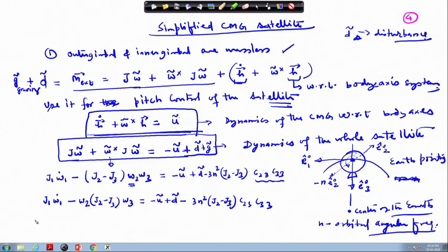Okay. So, omega 2 times omega 3, this can be written as omega 2 equal to theta 2 dot minus n and omega 3 equal to theta 3 dot plus n times theta 1, okay. And all the second order terms will be ignored. So, we look for the second order terms. This multiplied together forms a second order term, this multiplied together forms a second order term, this and this multiplied together does not form a second order term, because this is minus n times theta dot 3.